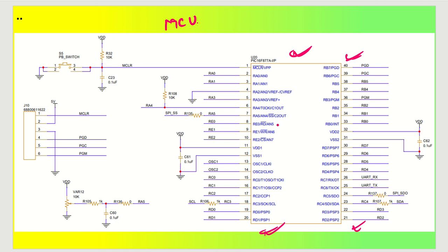Now very first thing what we will do is we'll try to concentrate where is my VDD pin. So this is VDD1 and VDD2, and this is VSS1 and VSS2. So this is power supply and ground pins. So I have kept a decoupling capacitor. This is called decoupling. So decoupling capacitors are actually needed. So you give your power supply with your decoupling capacitors. So that is more than enough. So your power supply is ready. Your device is ready to proceed. Okay.